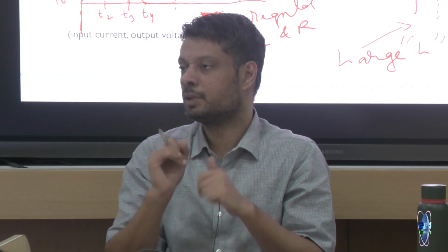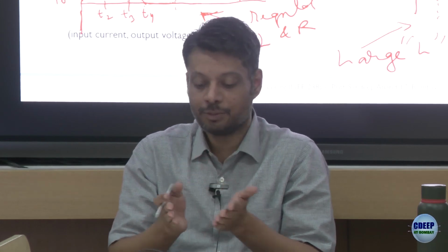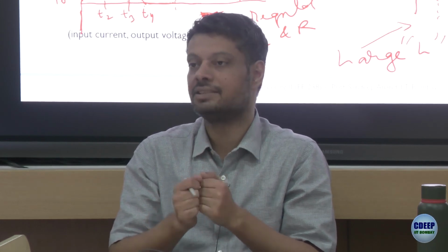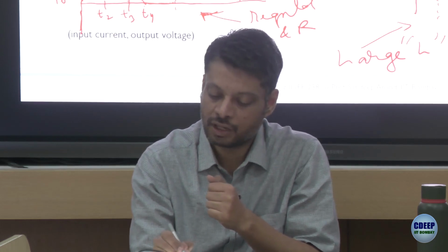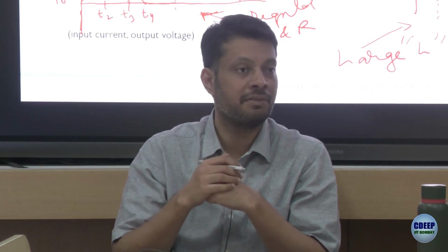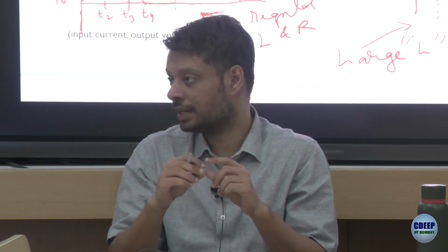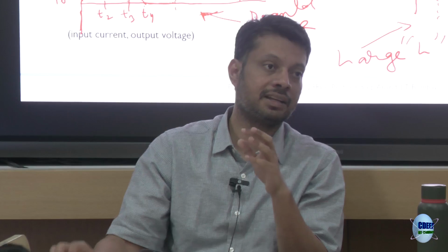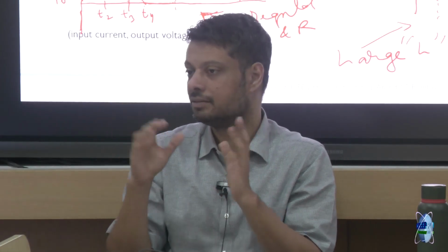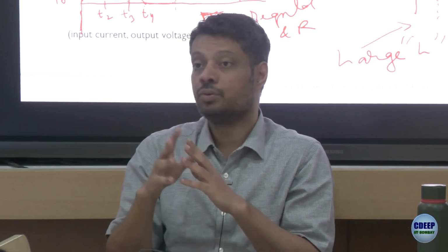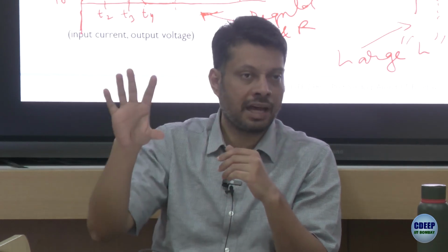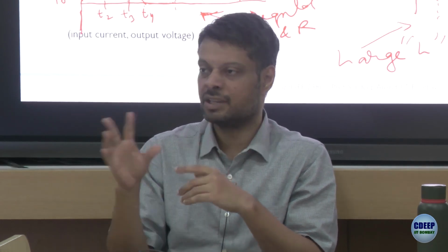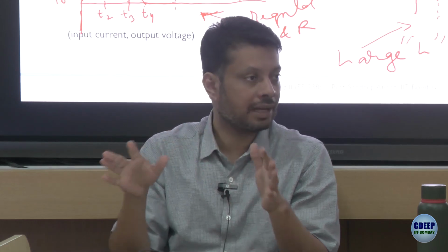Then assignment question number 2. Do both the things for a full bridge rectifier. You are not doing it now, do it for a full bridge rectifier. We did it for half wave, just one diode. Now you have 4 diodes. In the load, case 1, you can consider a pure R, which you know the answer. Case 2, an R plus L. Case 3, a pure L, right?